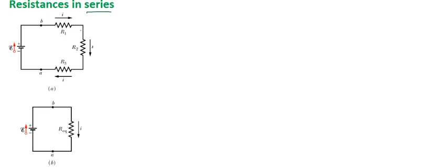The idea of equivalent resistance is, if I want to replace these three resistors with one resistor, what will be the resistance of that resistor? Whatever you see in series, it means we have the same current but different voltages. Whatever is connected in series has the same current but different voltages.